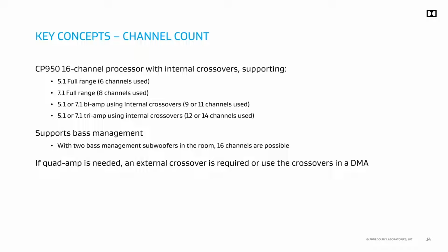The CP950 also supports bass management. With 2 bass management subwoofers in the room, 16 channels would then be the maximum output. If quad amp is needed, then an external crossover would be required, or you could use the crossovers and routing of the DMA amplifier downstream.